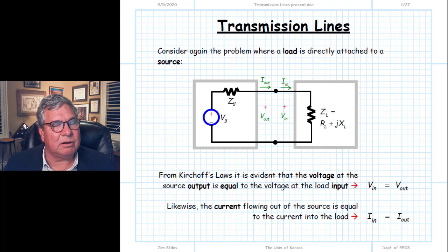So consider yet again our basic circuit where we've taken a collection of linear time invariant circuits or devices that may be very complex and sophisticated, and replace them with an equivalent circuit. If they deliver energy, then we can replace it with the Thevenin's equivalent. Connected to that is a sequence of very sophisticated linear time invariant electrical engineering, which we likewise have replaced with an equivalent circuit. And since they're linear time invariant, that equivalent circuit is simply an impedance, the input impedance of everything to the right of this plane, and that becomes the load impedance for this source.